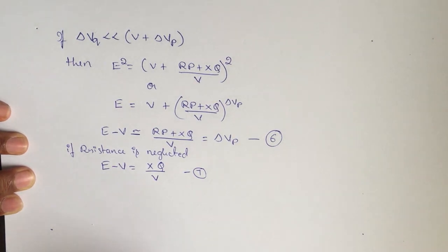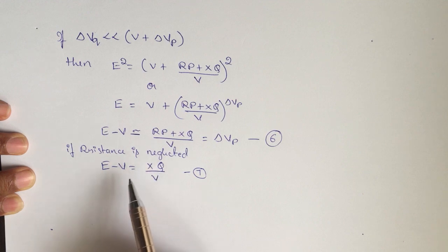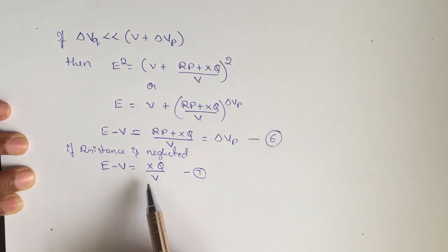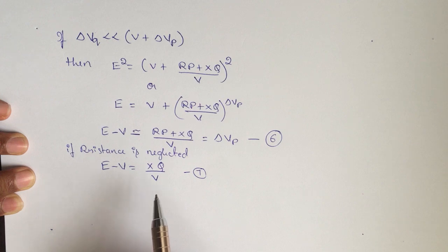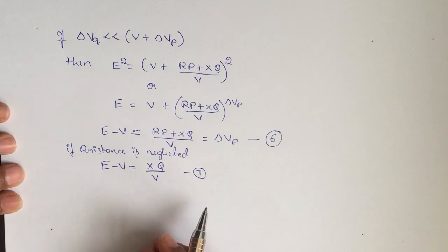Okay, so from equation 7 we can say that the receiving end voltage V depends on reactive power drawn by the load. You can observe here, the receiving end voltage V purely depends on reactive power drawn by the load at the receiving end bus. Remember, we are talking with respect to the receiving end. If we continue with the same to analyze more,